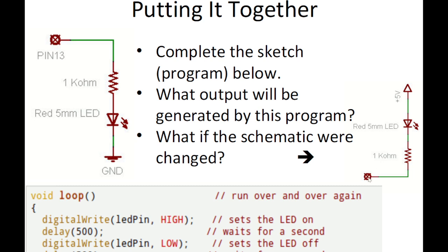Because this pin can be low or high, you can connect the LED in a reverse way, with the anode side connected to the plus 5 volt. So whenever the pin is 0, the current will flow and the LED will glow. Whenever it is 1, there is no potential difference, so the LED will be off.